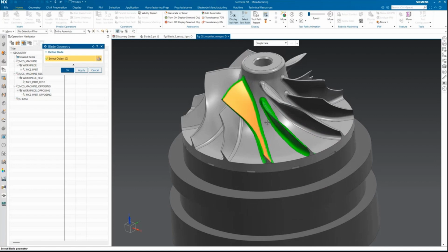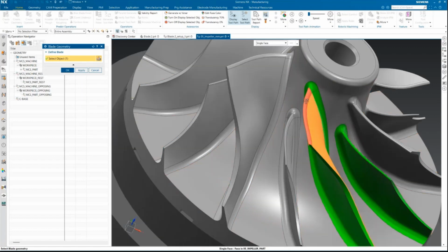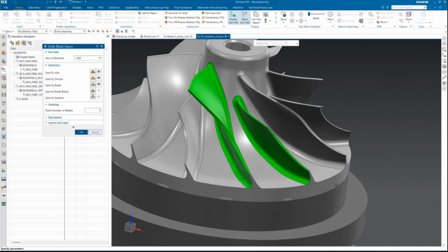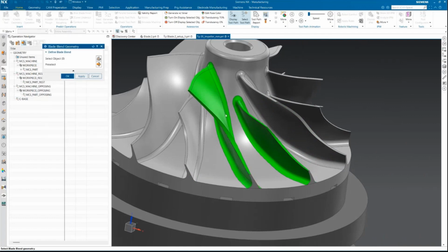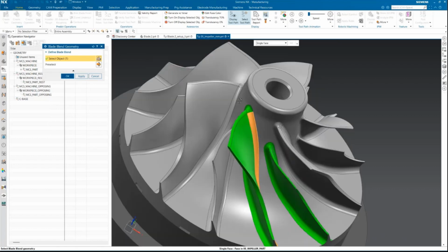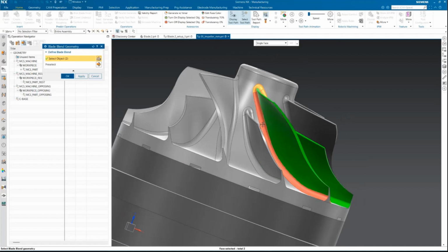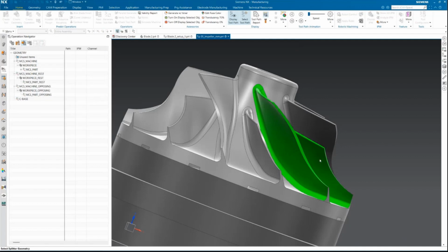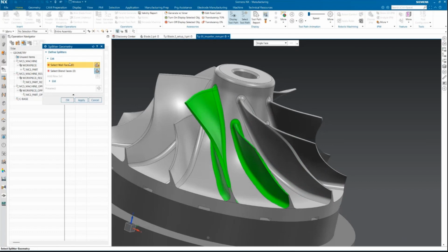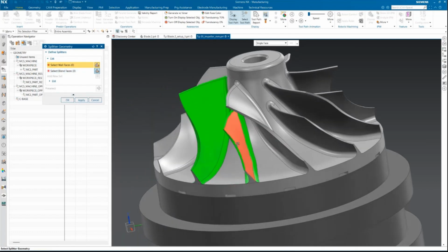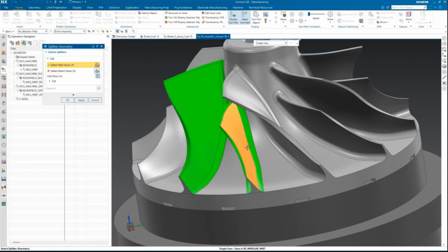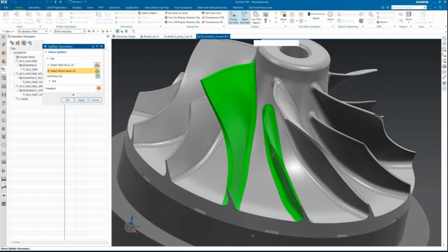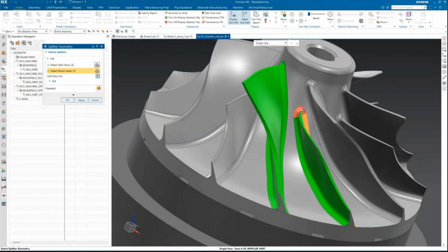While defining the blade geometries, it's always a good practice to follow the sequential format, and you have to follow the same method for the blade blend surfaces as well. You have to choose in the same sequence like you did for the blade surfaces. Whereas in the splitter surfaces, when we are specifying those surfaces, it shows us the options for the wall and the blend faces together inside a single dialog box. So again, the sequence should be followed for both the blade and the blend surfaces.